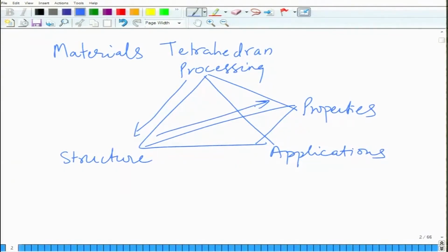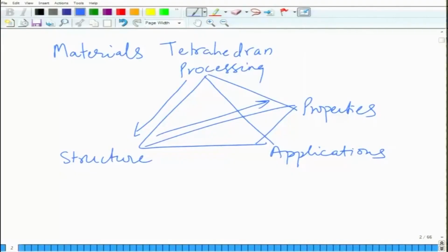Okay, a microstructure and nanostructure. Crystal structure is normally something which doesn't change significantly until you do some special kind of processing like non-equilibrium processing. So, under most processing methods, the crystal structures doesn't alter. The phase fractions may alter, and the microstructure may alter, which will give rise to change in the properties, and that will affect the applicability of the material. So, this is how these things are related.